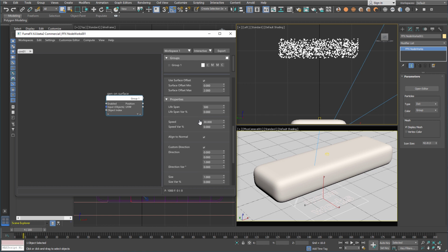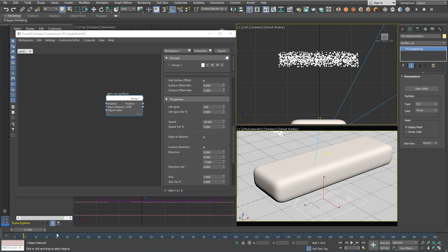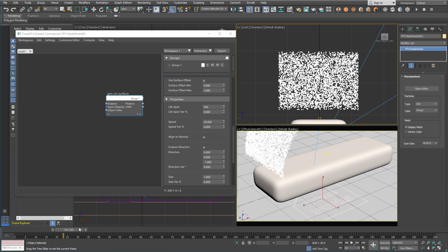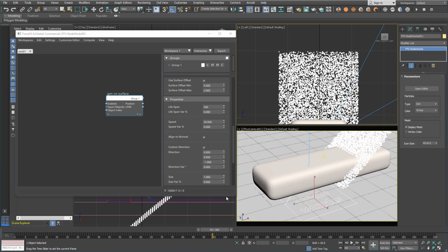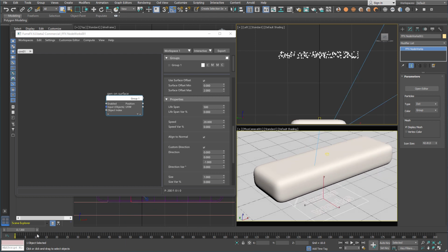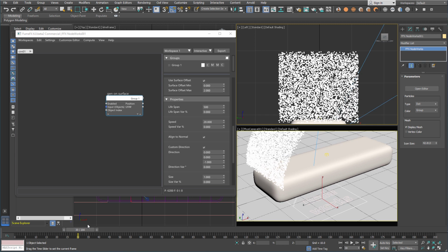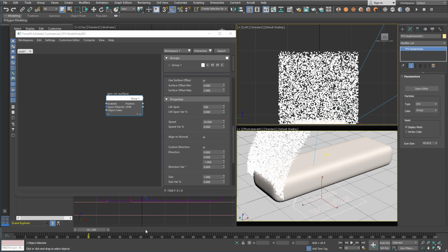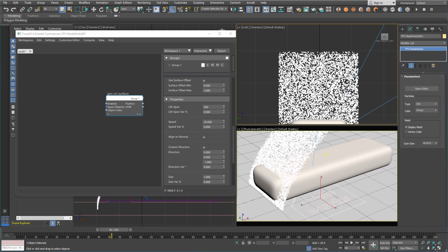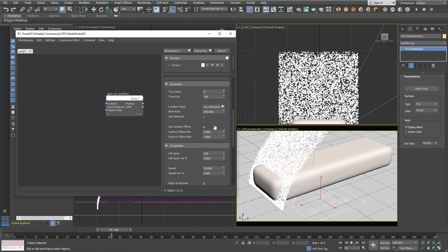This is a little bit too fast, so we're going to reduce this velocity a little and change the direction to the negative z-axis. This is just so we have initial velocities for particles, and later when we add physics, we're going to use physics gravity to pull the particles, as they collide with the biscuit, towards the collision plane. And that's so much about the emission.